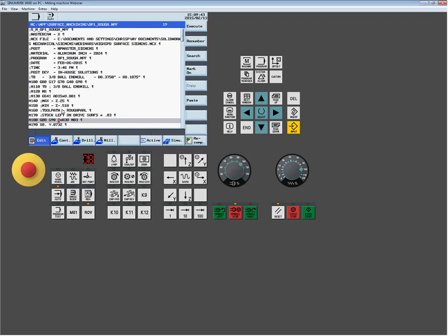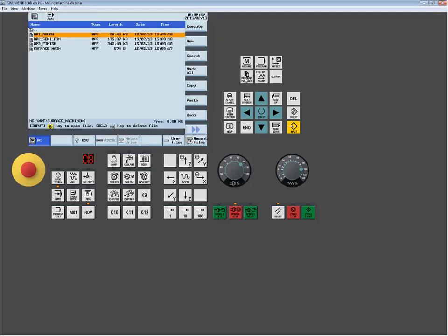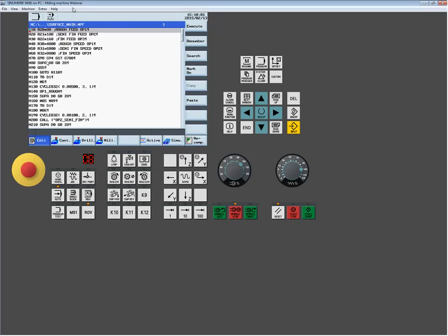Instead of having an S with an RPM, I can always substitute an equal sign and an R variable. This R variable is going to get written in one of 2 ways. First, if the main program is setting it. What I was doing before in my little program was right here with my R30, telling this I want it to run at 4,000 RPM.